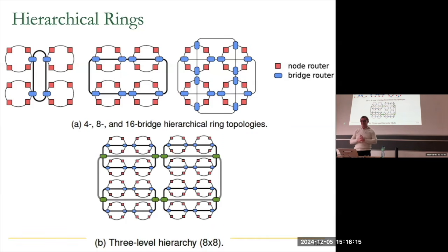in the best case. But if you actually rethink your topology such that it's more hierarchical, clearly you can have a hierarchy where you have a mesh, but then you concentrate, and let's say 100 nodes can be something else, right? Now you reduce the distance, clearly. But again, mesh has some issues in the sense that you only have local communication, right? And people have actually tried to eliminate that local communication. We did that, for example, with MECS network, multi-drop express channels.